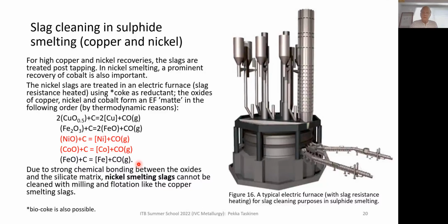Some smelters add sulfur into the bottom metal, into the electric furnace matte, in order to avoid any solidification of the matte, because when this iron concentration increases very much, up to 50% or so, and in cases where copper concentration in the bottom metal and in the raw materials is low, we may end up in systems where we have a mushy solid iron nickel alloy in contact with the molten bottom metal or EF matte.